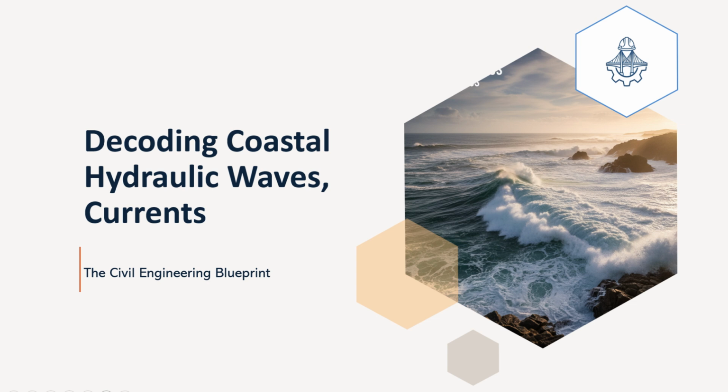This is truly powerful stuff for an engineer. And we even have real-world data that applies these concepts directly. Our source provides, for example, a wave record off Colombo port table. This contains actual recorded wave parameters like Hs, which is the significant wave height, often defined as the average height of the highest one-third of waves in a record. Tp, the peak period, the wave period associated with the most energy in the wave spectrum, and Tz, the zero crossing period, the average time between successive upward crossings of the still water level.